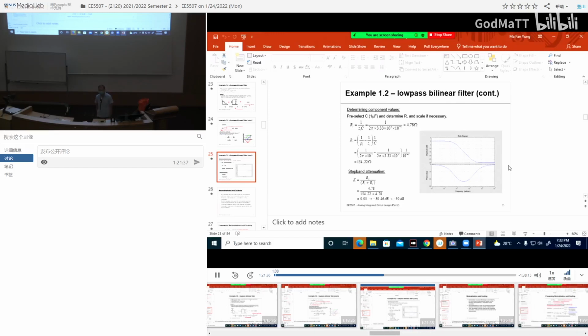First you hit the pole, which wants to give you a minus 90 degree phase shift when everything is stabilized. Then you hit the zero, which wants to give you a plus 90 degrees at very high frequency. So they cancel one another. That's why the phase shift is 0 at DC and 0 at very high frequency. In between, there's some disturbance because you hit the pole first and then the zero later.